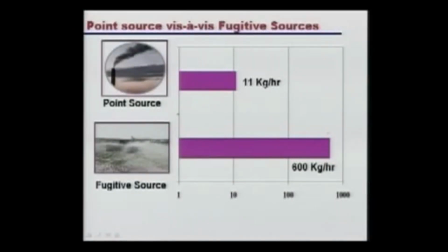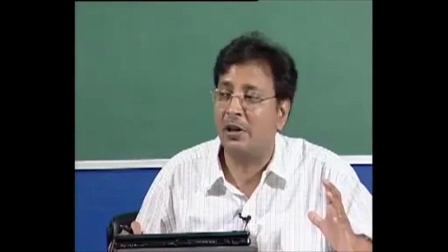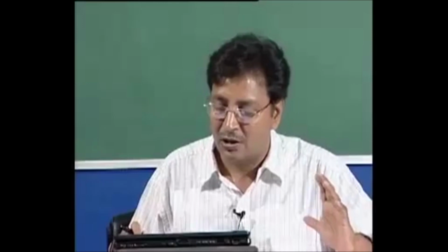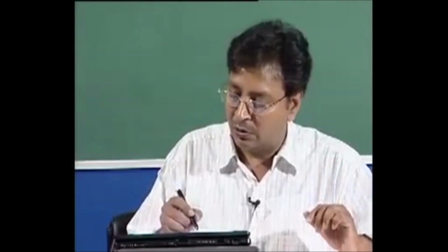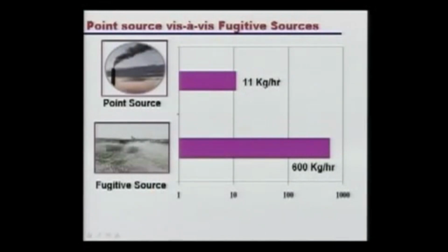Finally, interpretation is a very important part, and a person gets a better feeling for what is important when things are shown in the relative sense, because absolute numbers sometimes people don't understand. For one study that was done, you see here the regular source from the chimney, which is very highly controlled, with lots of money spent on ESPs and bag filters, and no one was there to take care of the fugitive source.